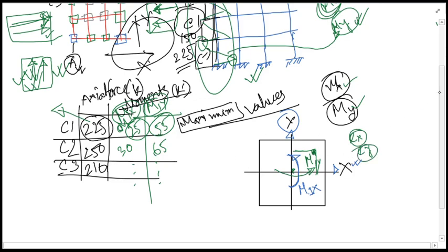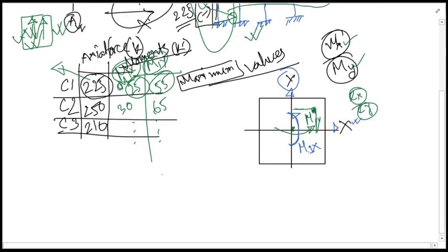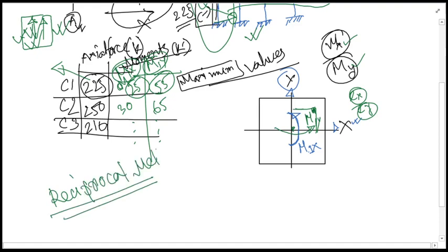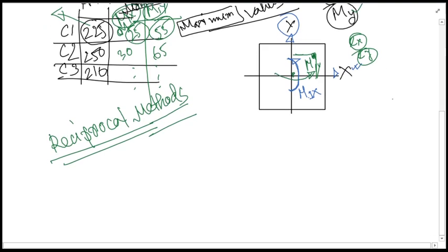Therefore we cannot proceed as for concentric columns. The formula will not be valid there, and so there are two methods, from which we will be using the reciprocal method. You might have learned about the reciprocal method for designing eccentric columns. That method will be applied here, and for that there are some different charts which we'll be learning one by one.